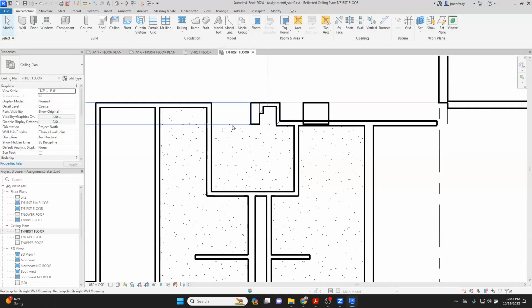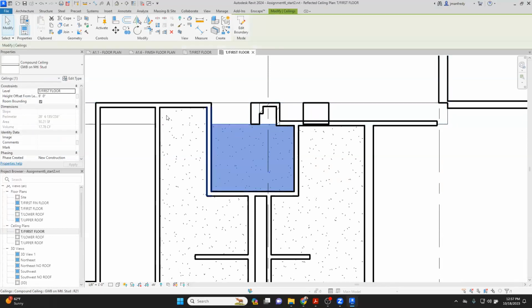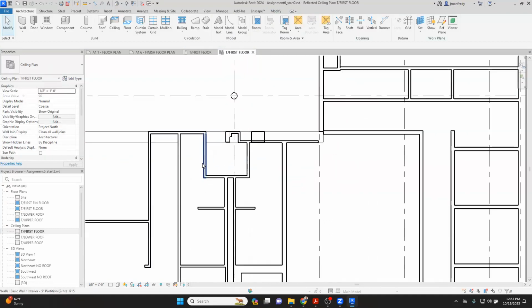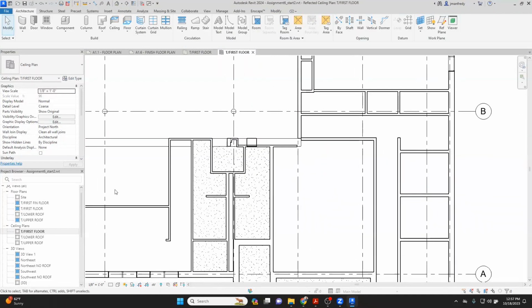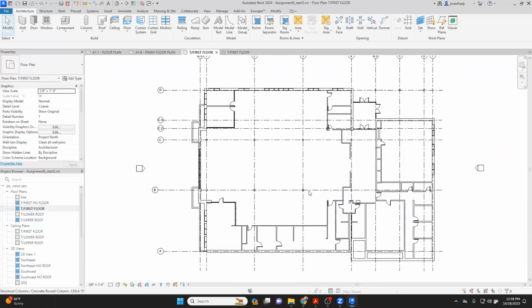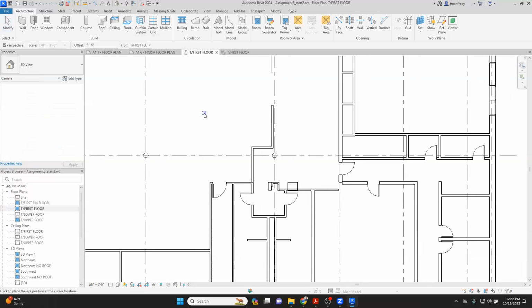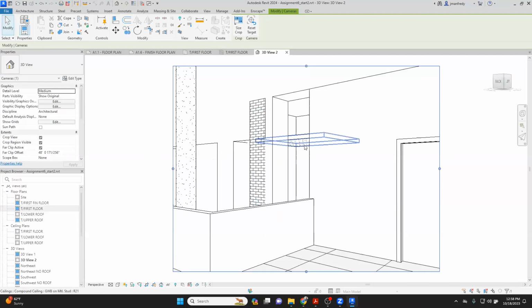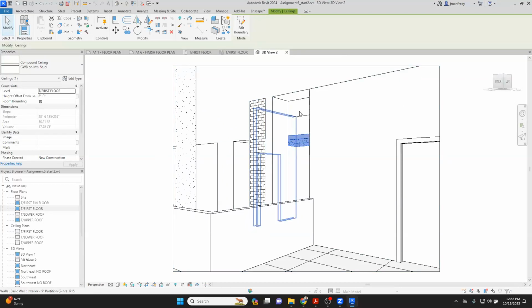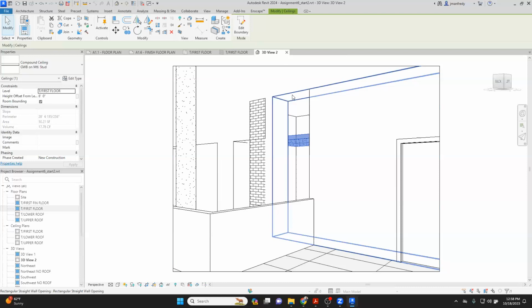This ceiling here is at, that ceiling's at 8 feet. Not supposed to be. And I suggest you start taking tours of your interiors to test the model. So if I were to stand with a little camera right here on the floor plan, stand here in front of that doorway looking into the bathroom, you can see there's a ceiling floating down here, but the opening in the room is way up there.